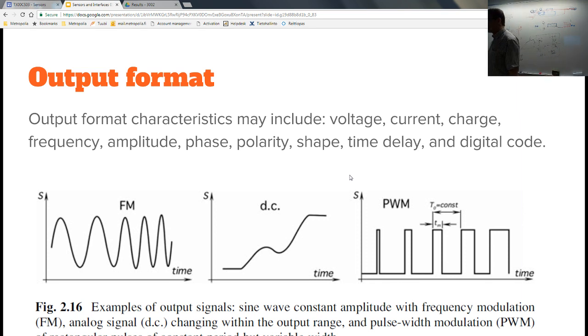And if you have capacitance and you have inductance, what do you have there? You need just the excitation, and you have an oscillator, feedback and excitation. And basically you can measure the capacitance based on the frequency, the fundamental frequency of this LC circuit.